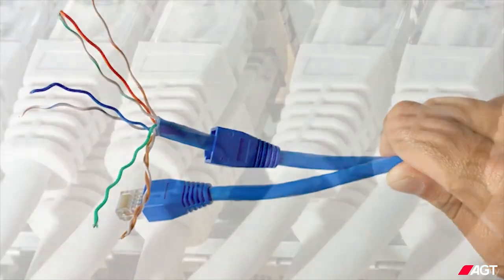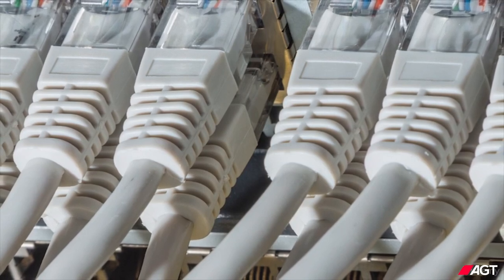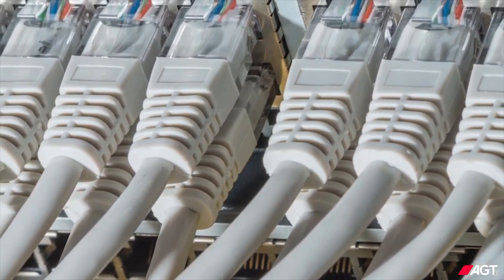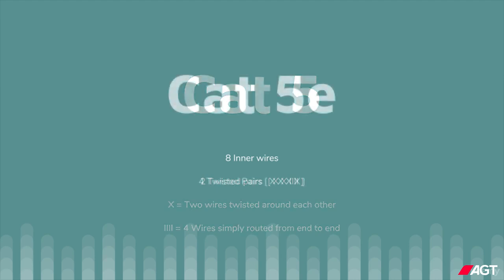All Ethernet cords, regardless of category, contain the same 8 wires. It's how they're arranged that changes their speed and latency. So, in order to appreciate Cat7, let me quickly go over the previous categories and show you how they've improved. So, the Category 5 cable has 8 inner wires, but it has 2 twisted pairs inside. The twisting method is what helps keep out interference. Now we look at the Category 5e. It's got the same 8 inner wires with all wires twisted, so we have 4 pairs of twisted wires. This reduces interference and crosstalk even more.